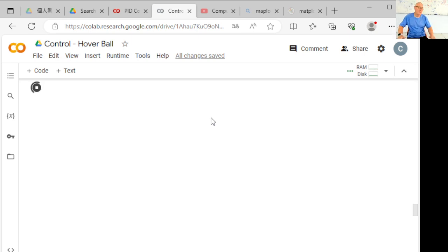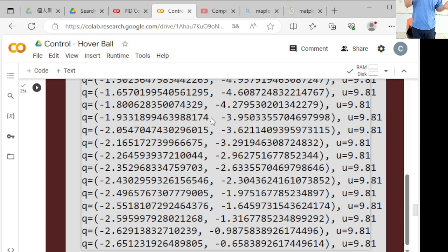And like I said, for the hover ball, you need to know the current velocity, and therefore you need to time when you hit the lower gate and when you pass the lower gate upwards, because that allows you to back calculate what the velocity was when you hit it, which allows you to turn off the magnet before you reach the upper gate, right? Because what you want is for the ball to basically just hover up there and hit that position at basically zero velocity, right? Then it'll start decelerating again.